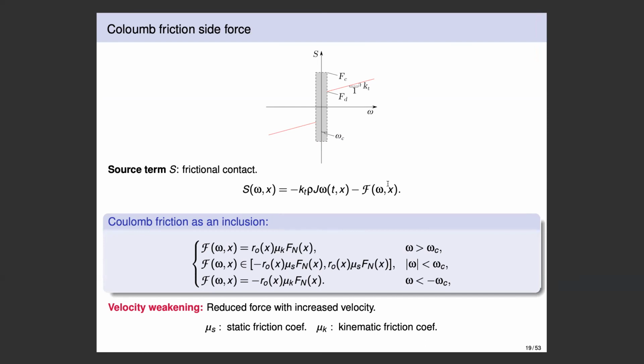Because we notice when we use a model that there is a lack of account for the curvature in the calculation of Fn. So the side forces are completely wrong in kickoff parts. Okay, we need to talk. I would say that's the main thing that plays a role in this equation. There is this capstan effect in kickoff parts because of the curvature that needs to be accounted for in the side forces. If you don't account for that, then you are underestimating Fn. Okay, then I understand what you mean. We have a 1D model of the drill string, so we only take the effect of inclination, but not of the curvature. Yeah.